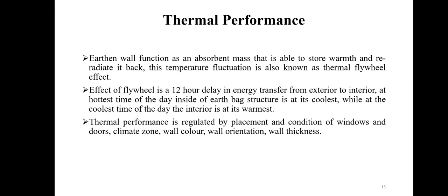Thermal performance. Due to the earth walls, the inner part of the house stays cool and absorbs heat. There is a flywheel effect. So what is the flywheel effect? There is a 12 hours delay in energy transfer from exterior to interior or interior to exterior, which is known as the flywheel effect.